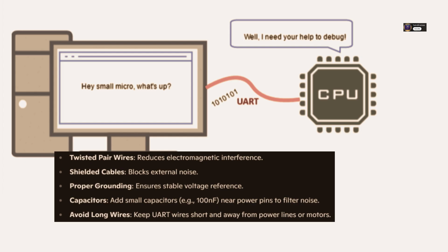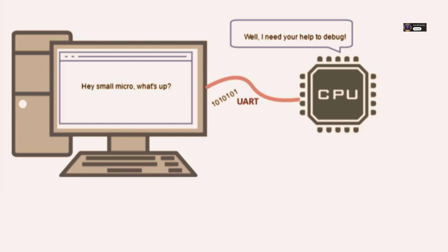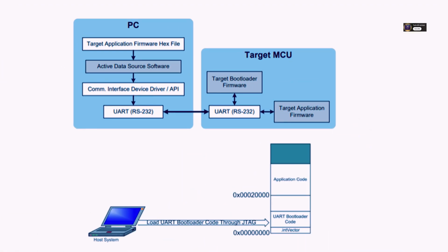Have your microcontroller firmware programmed to receive UART data and maybe blink an LED or, even better, echo the received character back to the terminal. 8. Check if the LED blinks or if the character you typed appears back in the terminal. This tests PC TX to MCU RX to MCU TX to PC RX. Full loop. If both steps 6 and 8 work, your basic communication link is functional.